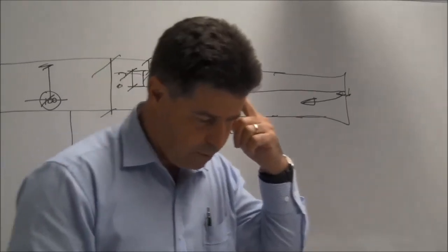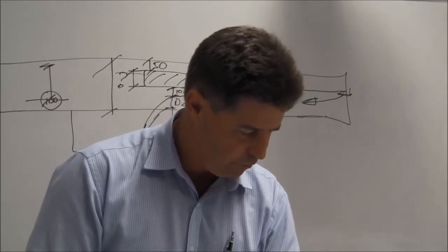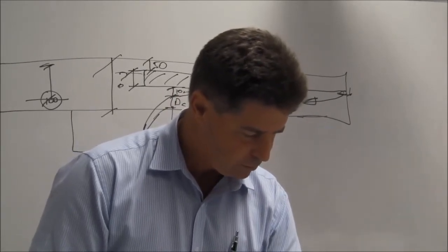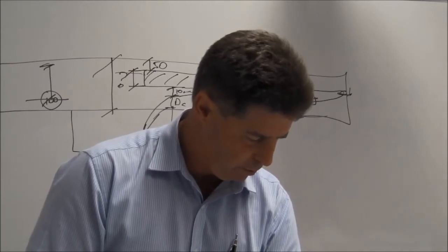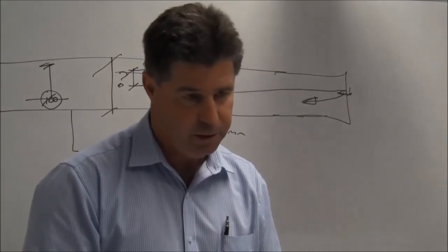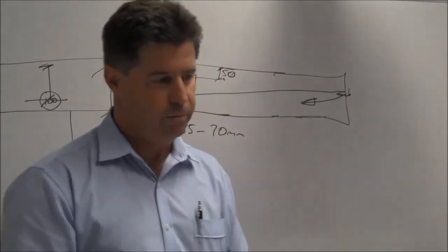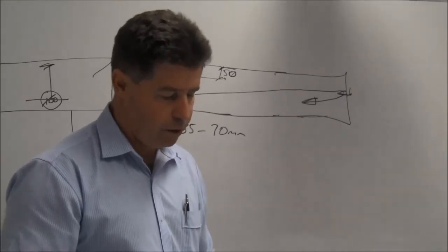If you go back two paragraphs above where I've got my 30 mil, I've used an overflow size of not less than one-fifth, and a head of water over the overflow outlet of 50 mil. That's where that 50 is coming from. Like I said, it could be anything.